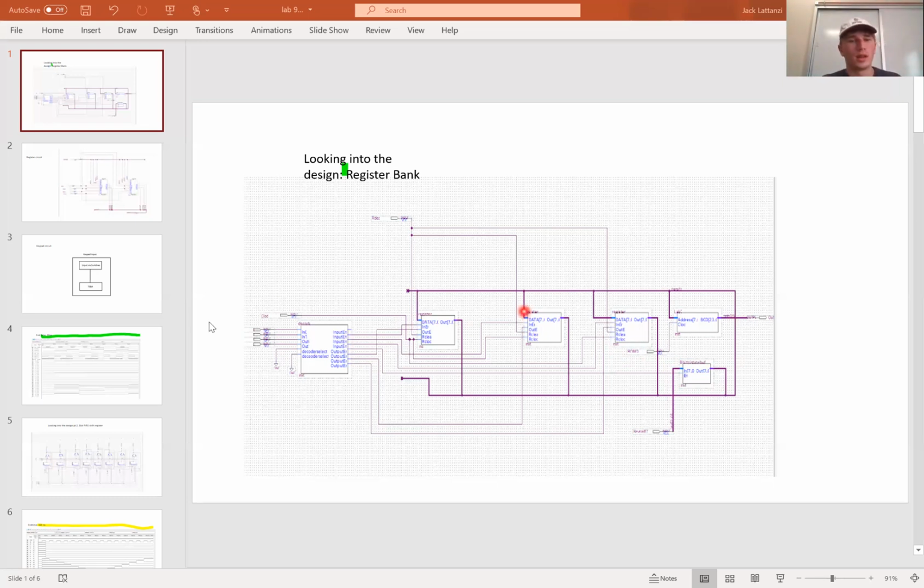And then when the output is enabled, so say we put 1 into register 1, so it's 0, 1 for the input enables, and then you put 1 for output enables, so 0, 1, then it will give the output of this register and go around here and display it, and it will enter the binary to 7-segment display and display it.